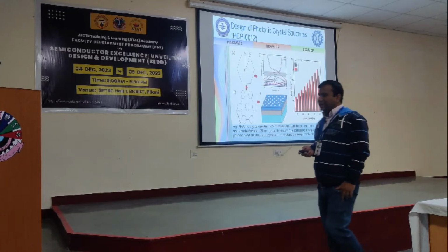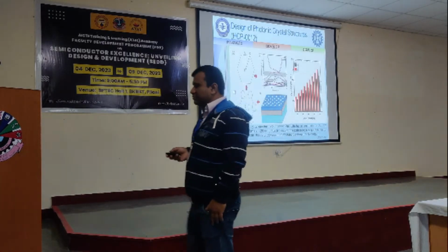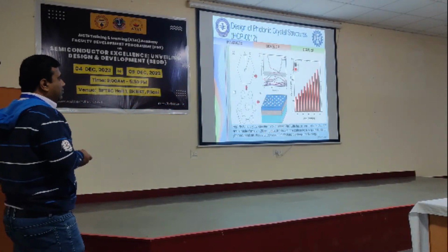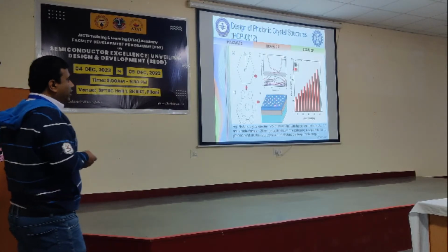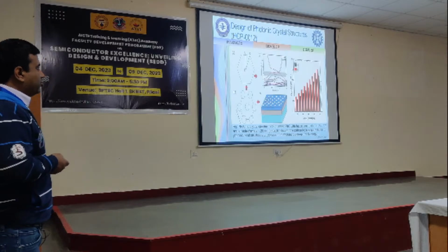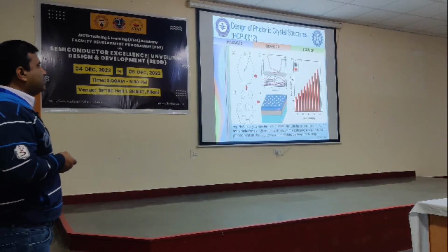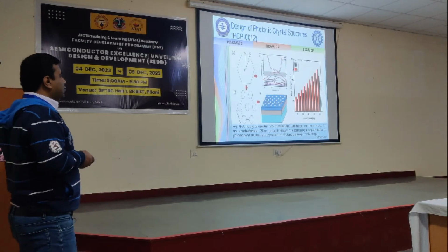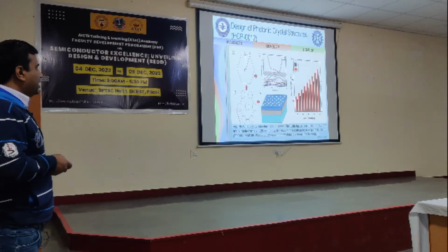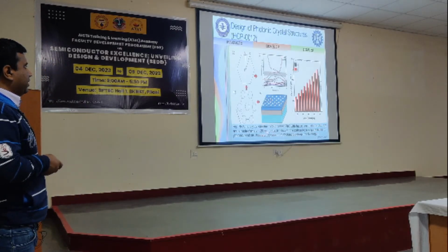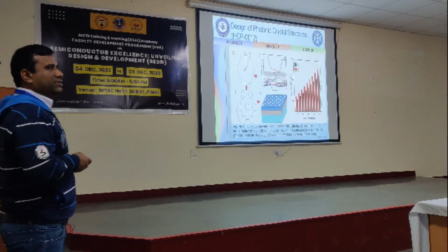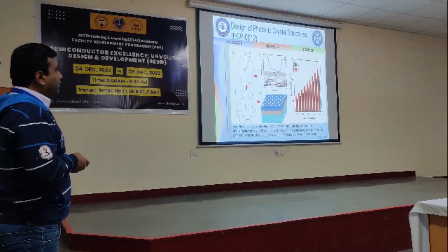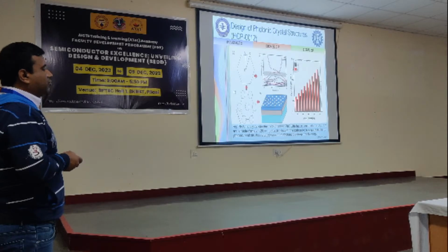Now this is the design of photonic crystal based devices for biosensing applications. You can see this is the SOI substrate, silicon dioxide, and this is another upper silicon layer, or device layer. The silicon is patterned in such a way that you can achieve a photonic band gap in this region. By simulating the device, we have found that the lattice constant should be 200 nanometer and the hole diameter should be 120 nanometer. You have to tune or optimize the device in such a way that upon applying incident light, your reflectivity or wavelength should be in this photonic band gap region.